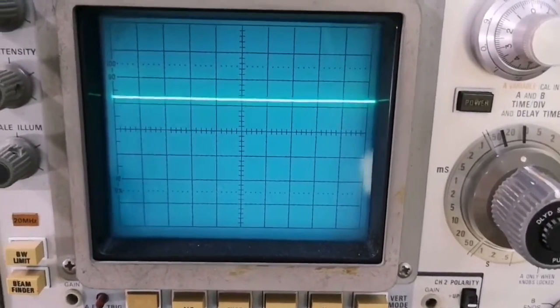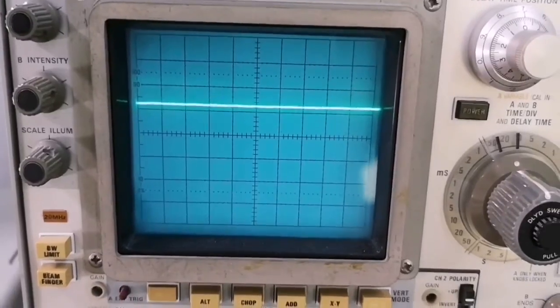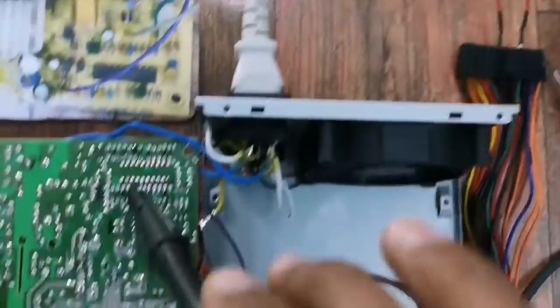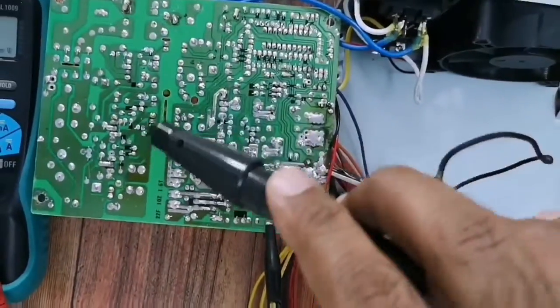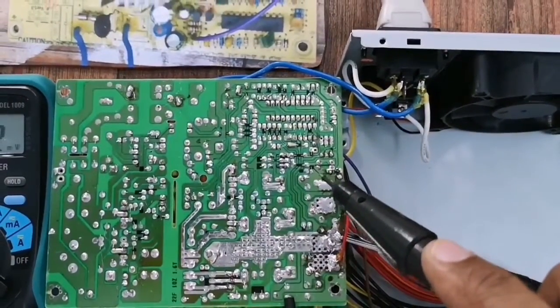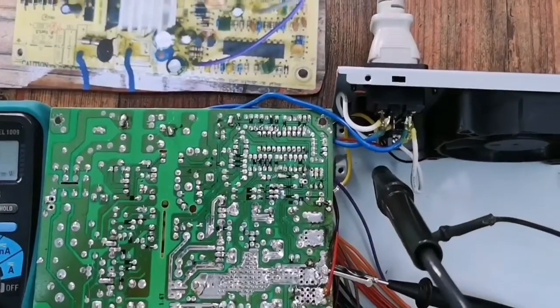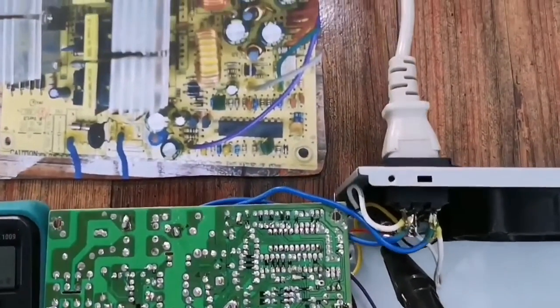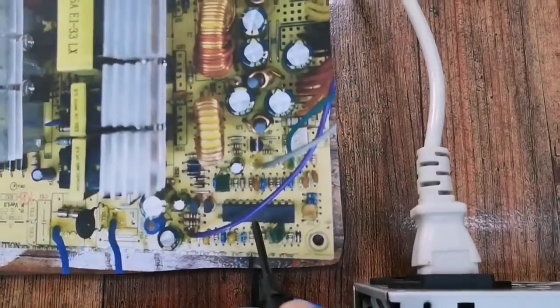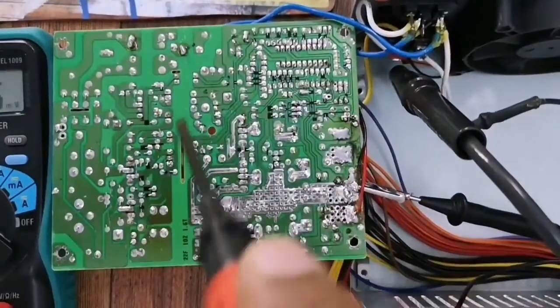It keeps oscillating on and off, and I think I can explain that. In this type of power supply, when we have overcurrent or overvoltage, undervoltage at the output voltage stage, this effect is happening. So the IC is getting shut down by this and then restarts, and it just keeps doing this.